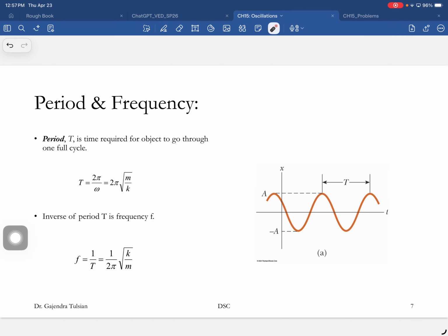So you guys understand simple harmonic motion? It's extremely important. Anytime you have to study vibrations, you bang the table, each element is undergoing simple harmonic motion. You guys have seen satellites launch, and then they unfurl those photovoltaic cells, and more often than not, those things are vibrating. You don't want those vibrations to get out of hand. You can analyze it using simple harmonic motion.